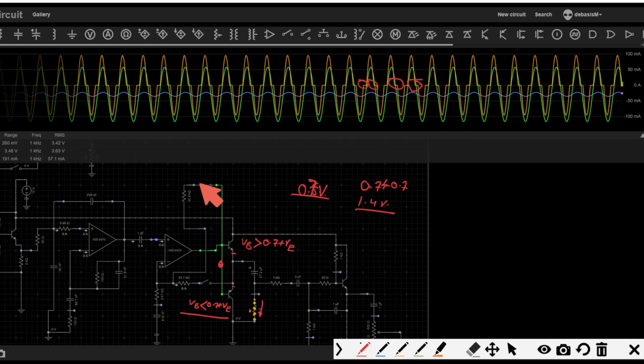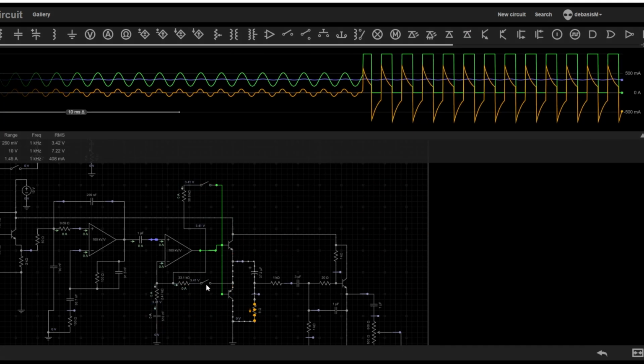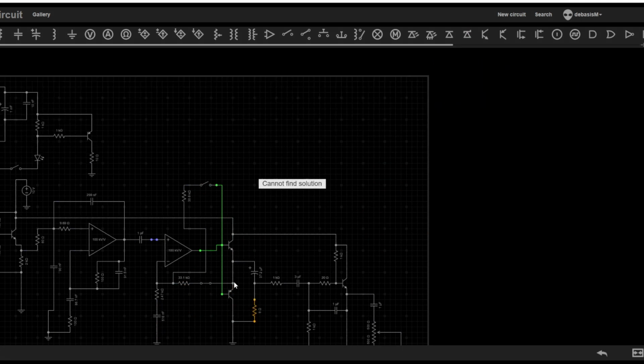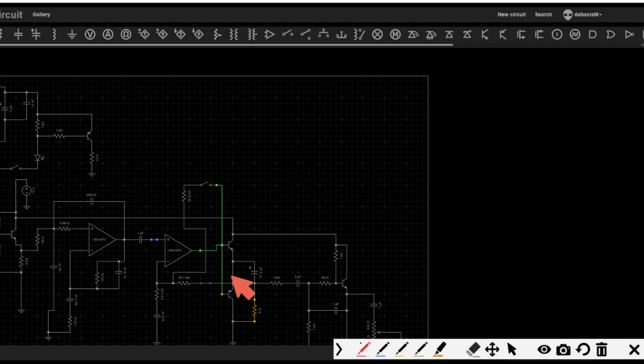This was my objective, to put in this switch and make this circuit. Otherwise this circuit doesn't exist on the board itself. Now let me proceed to how this problem is solved in this IC. Here it's a very smart way. You have a feedback from the transistor output itself, this point. In a smart way, the feedback is taken from this point, which is the main current flow path for the transistors. From here you have a small resistor and then feedback to your inverting terminal.